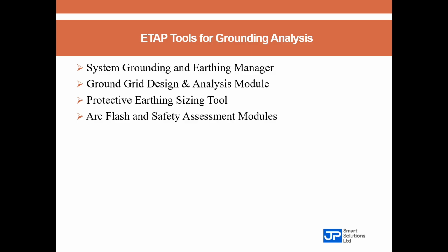So grounding doesn't just affect protection, it affects measurement, safety, communication, and compliance. Every time you export any ETAP result for a project, ask yourself this question: did we model the ground? Did we model the ground?